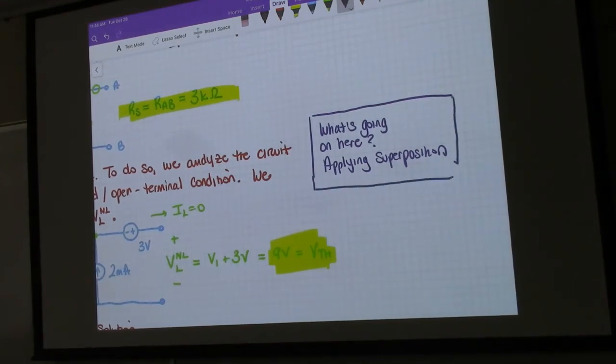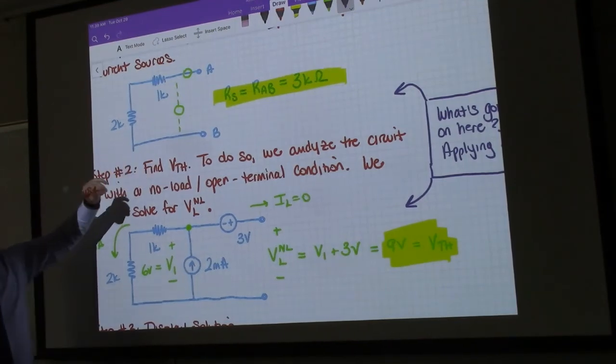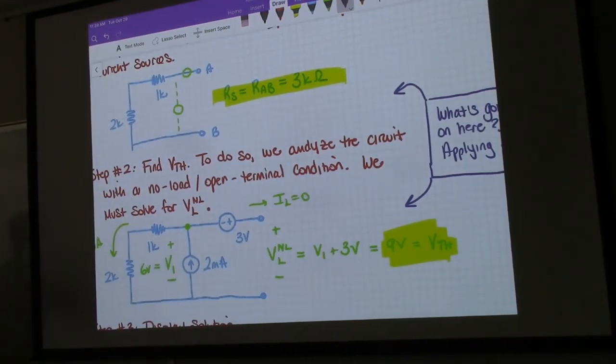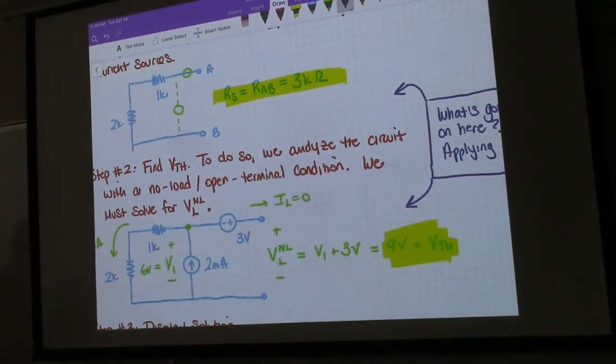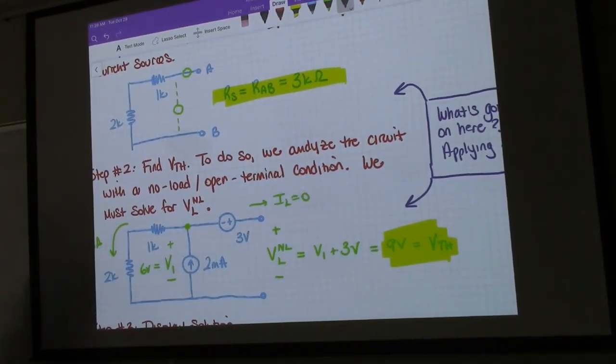The basis for this method, you can see, is splitting up the circuit into essentially two different versions. This only works because of superposition and because of linearity, and that's again the reason why it's a condition for finding the Thevenin or Norton equivalent that the circuit is linear. If superposition didn't apply, we wouldn't be able to find the equivalent resistance by simply pulling the sources out. That's a capability we get because of superposition.